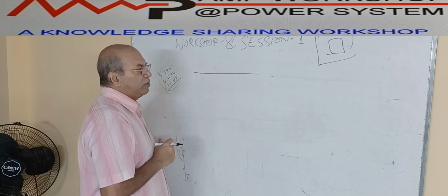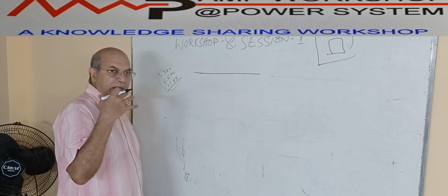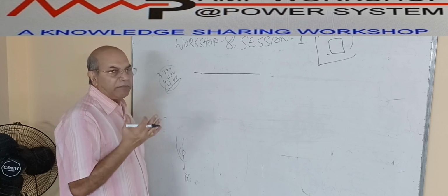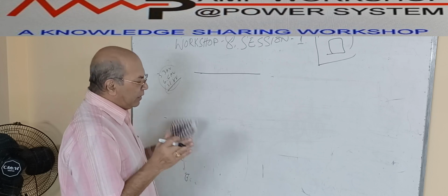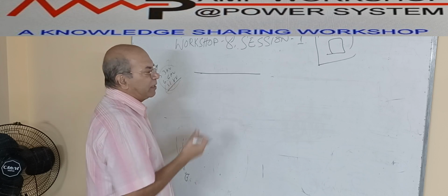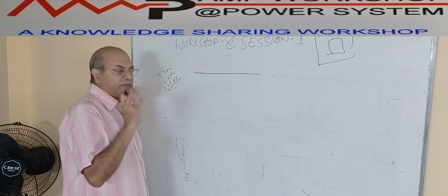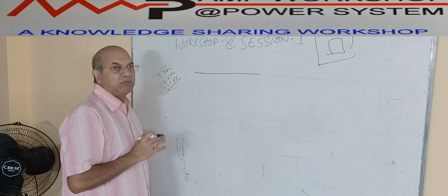The GIS switchgear advantage is that the dielectric strength around the power components is very high, because it is SF6 gas, so the inside space needed is very small. So in about one third of the space we can install the same switchgear, but as the components are fixed, we do not get these drawout features.